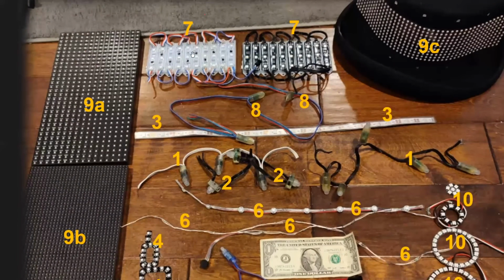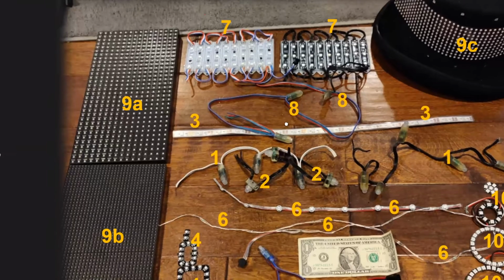Up here, number 7, these are modules. I call these modules. These are the standard 3-pixel on a plastic mold, if you will, modules. Number 8 here is what are called strobe pixels. As far as I know, I'm one of the few that use these. You're welcome to look into them. This is a strobe rather than being a standard RGB LED. This only responds to red and white, and it just strobes a white color. It's white only. These are strobe pixels that you can use.